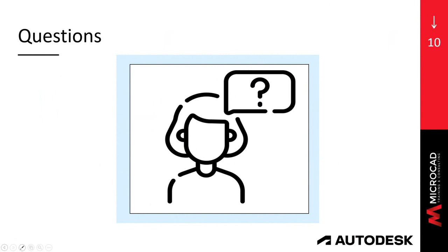I would say between 50 and 100 gig, not more. If it's bigger than that, just review what families you have loaded in there. You can always lean up your templates. As I mentioned, you don't need to have all your components loaded in there. Just remember that Revit is a memory hog. That file that I showed you from 300 gig, I leaned it down to 39. And it's still evolving. I think when it's done, it's going to be 50 gig. And that is a good file size to start with.